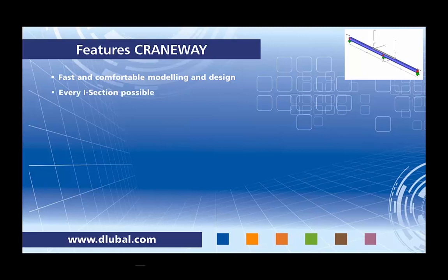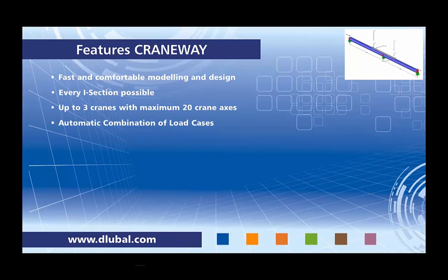You can use every I-section, like welded or rolled I-sections, and you can strengthen them by channel profiles or angles. You can define up to 3 cranes with a maximum of 20 crane axes. And one of the biggest advantages of the standalone module CRANEWAY is that you can have an automatic combination of load cases for different design situations like fatigue, ultimate limit state, or serviceability limit state.